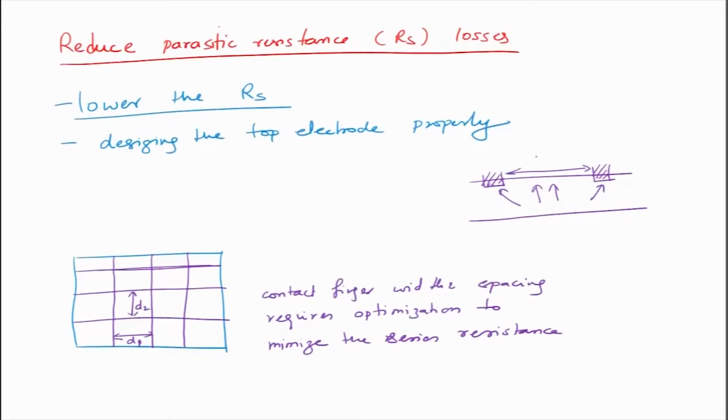So, the distance between these contacts is extremely important, and the depth up to which they are buried into silicon is also extremely important. So, one needs to control the spacing. Spacing means both the width and the spacing, but one also needs to control the doping around it.